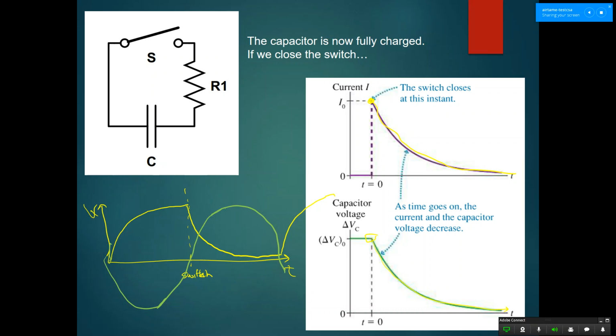With DC it would be totally straight, theoretically, right? AC is taking turns going in both directions. So at some points it's going to be dropped, at some points it's going to be high. So if you can put it in sync with the capacitor charging and discharging, then you could create a situation where you have almost always a high voltage, which is what your devices need.